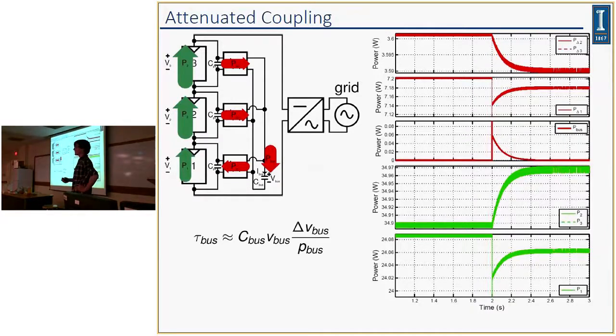It's like 30 millifarads. So what you have is the same sort of situation. At 2 seconds, converter 1 perturbs, and over about 0.2 seconds, which sort of corresponds to its time constant, it's no longer an impulse. It holds on to its sourcing power, or its sinking power, for a much longer amount of time.